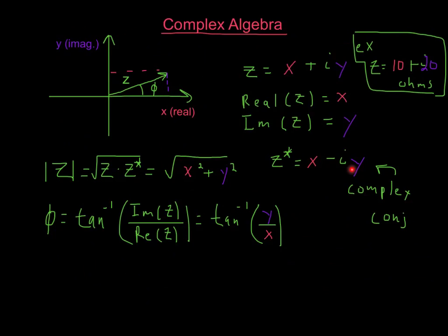I'm also going to be interested in the phase of V out over V in, and what that tells you is, if you put a sine wave into a circuit and you look at that sine wave compared to what comes out, you want to see if they come out with any phase difference. That's very important. You might put a sine wave into a circuit, and then you look at the input compared to the output, and they're right on top of each other, so that would be zero phase. There would be no phase lag or lead between them. However, you might find that the one that comes out is shifted 90 degrees out of phase. And this can actually matter when delivering power to loads and circuits.